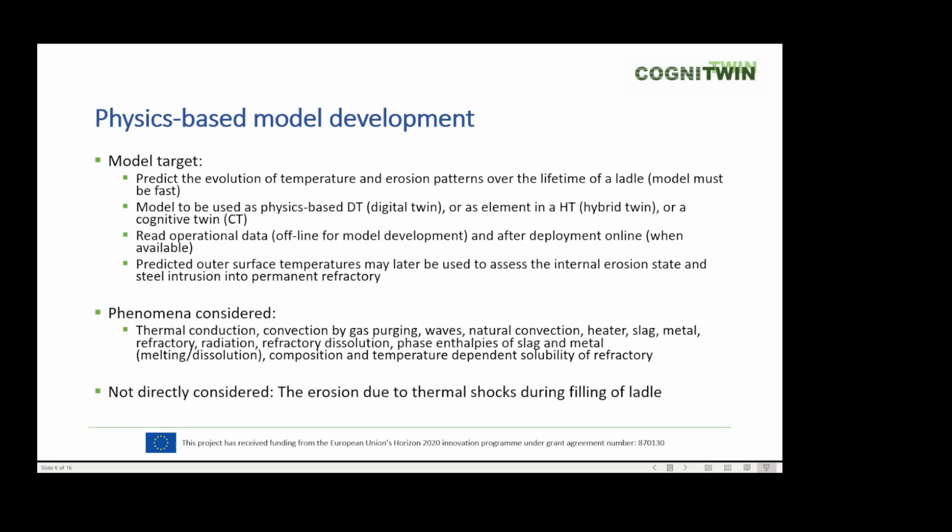The phenomena the model is considering are thermal conduction in the materials and between materials, convection by gas purging, waves on the surface, natural convection when there is no bubbling, the effect of the heater, what happens with the slag and the metal, the refractory, and we have thermal radiation, and refractory dissolution into the liquid steel and slag.